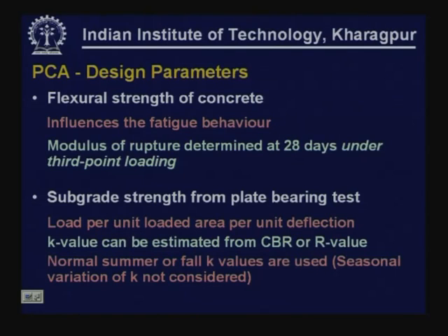The flexural strength of concrete influences the fatigue behavior of concrete. Modulus of rupture determined at 28 days under third point loading. How this has to be obtained is also specified. Beam specimens have to be prepared, third point loading has to be conducted, and the modulus of rupture obtained from the test at 28-day period has to be used for design.